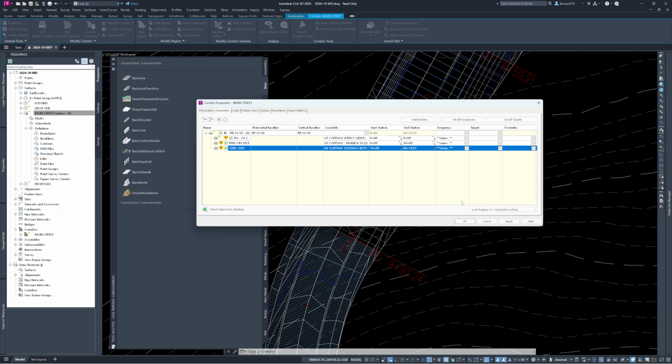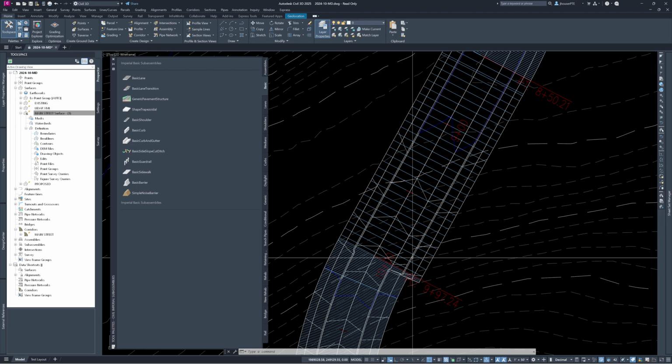Okay, so yes, the transition, as you can see, is not quite right. We have other techniques that we can do to make the transition much better. You can see it bumped it out a little bit, 1 foot on each side, and then put the parking on the side. But it did put that all in. It graded it off until, so no, actually it looks like it lost its daylight.